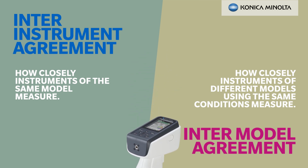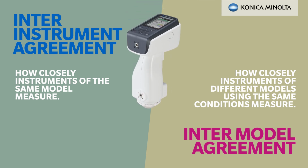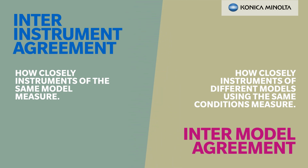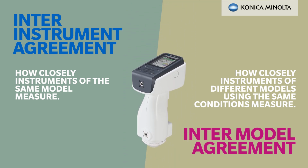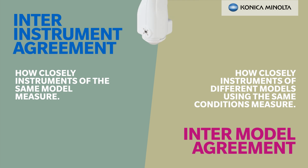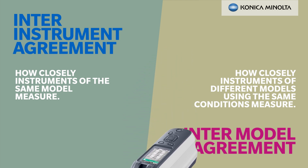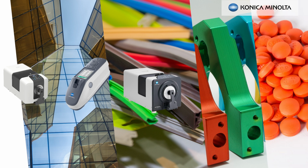This is because instruments have an inter-instrument agreement, a tolerance of how closely they read to other instruments of the same model, and an inter-model agreement, which is how closely they measure compared to another model of instrument otherwise using the same conditions. The inter-model agreement will introduce the larger margin for error, but in some cases it can be an acceptable error. Inter-model agreement is influenced by the differences in geometry and the components and materials used in the different models. If you consider measuring your products with two different models of spectrophotometer, please check for inter-model agreement for each of your applications separately.